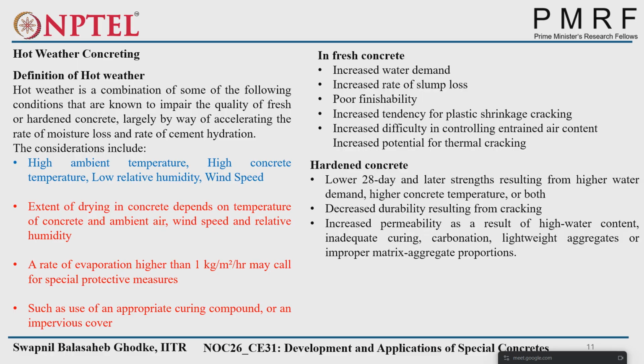Now hardened concrete. As I already said, the water demand increases, so the 28-day strength is lowered. It also affects the durability aspect because of the shrinkage cracking. Because of the evaporation of a higher amount of water, there is a chance of more pores, which will affect durability and increase permeability.